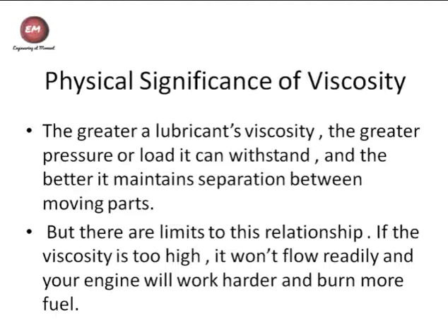But there are limits to this relationship. If the viscosity is too high, then the fluid won't flow readily, and your engine will work harder, and it will consume more power, and then your fuel efficiency will decrease because your fuel will burn more. So viscosity has appropriate specifications according to its application. According to application, there is a particular specification of viscosity.